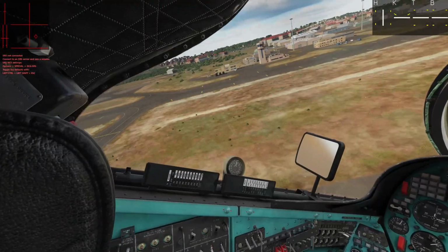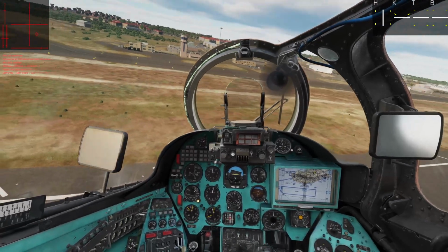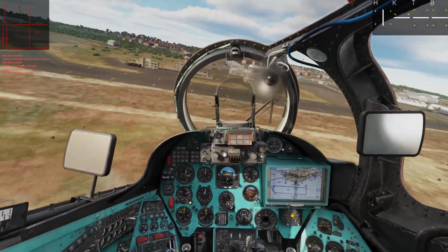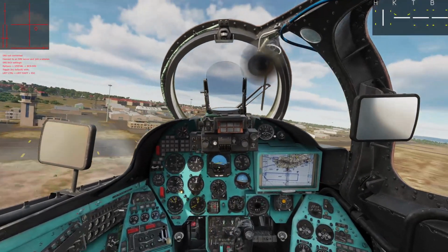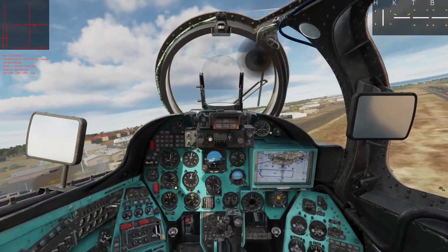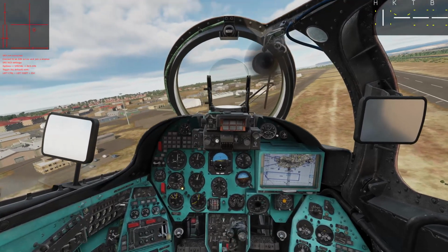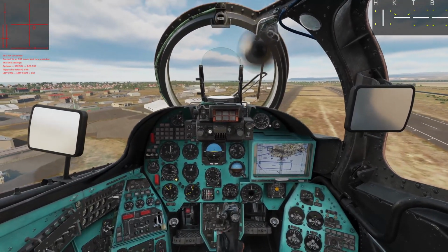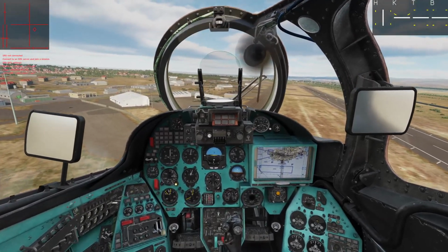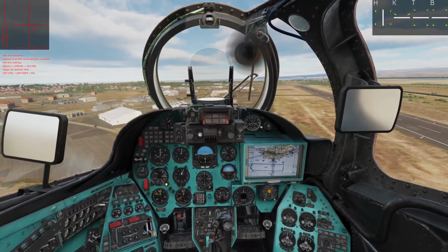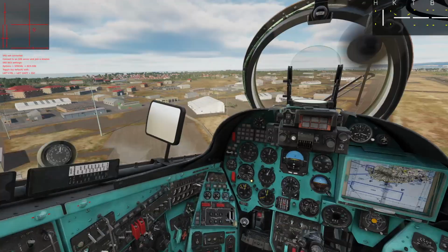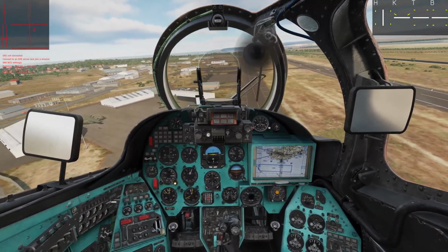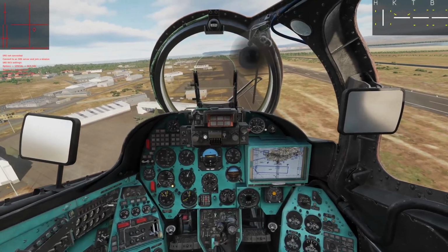So, what do I think is happening? I think what they're trying to do is simulate tail rotor VRS, what I alluded to earlier, and loss of tail rotor effectiveness, or what's commonly referred to as LTE. I think it's happening way too easily. I think it's entering the vortex ring state really too easily.